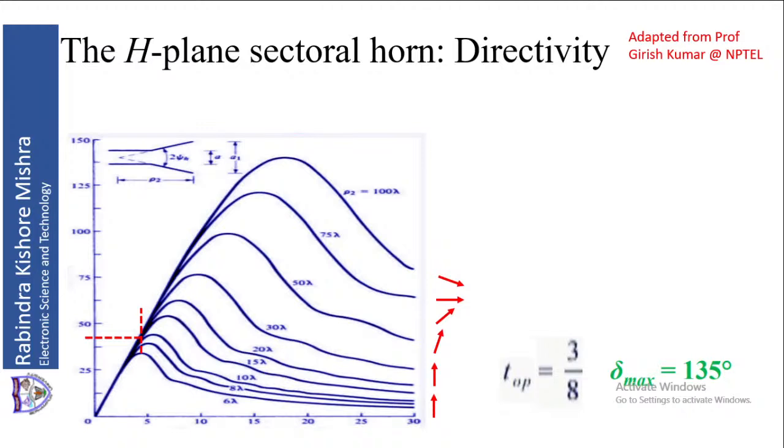So we should minimize the phase error. We should not allow this much phase error to get a good directivity. I will discuss that in the next slide. This will be more clear. You can say we are getting this much high directivity. Why should you reduce the phase error? You will shorten the aperture and get less directivity.